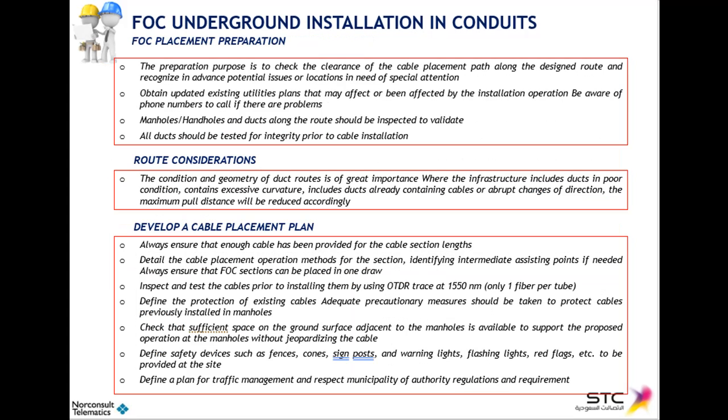Just a very basic additional requirement. Prepare the location where you are going to install the cable. This is all we say here. Prepare the place, so you have enough space to organize and place your installation equipment properly. Get the utility plans that may affect the route. Inspect the handholds and manholes according to the network survey requirements, and test the integrity of the ducts.